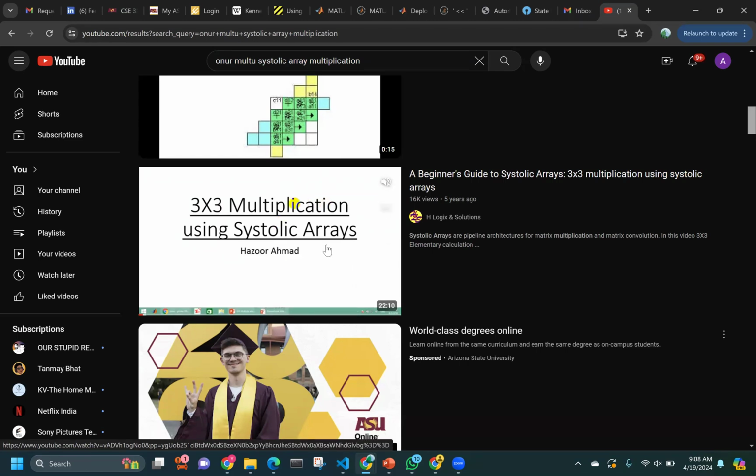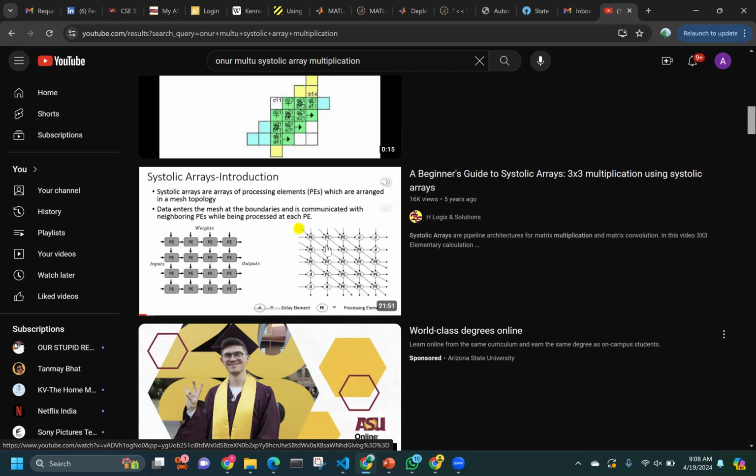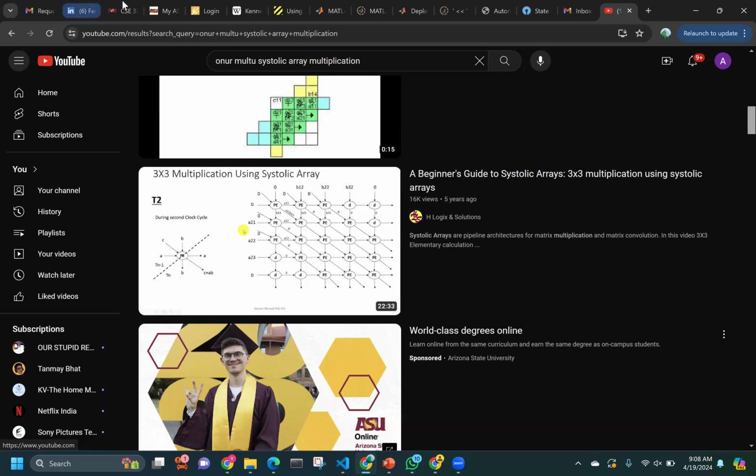Similarly, a PE description is already given to you in the template code. You have to instantiate or map the wires to the inputs and outputs of the PE such that it works in the systolic fashion. So it is important that you understand this video and how a systolic array does multiplication before proceeding to use the code and implement the matrix multiplication.